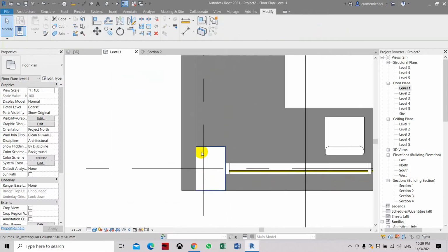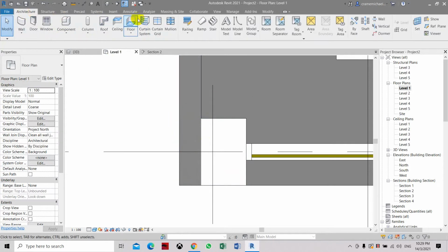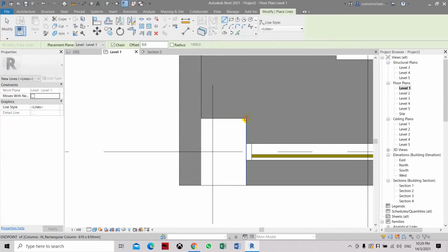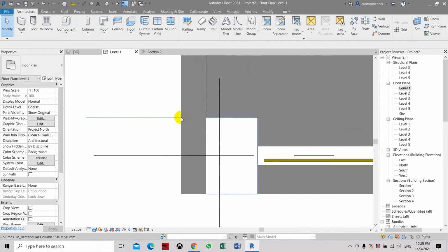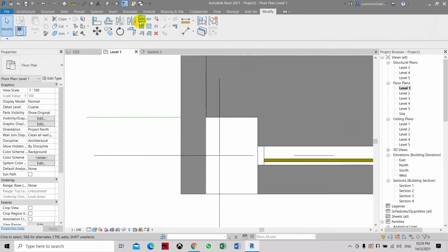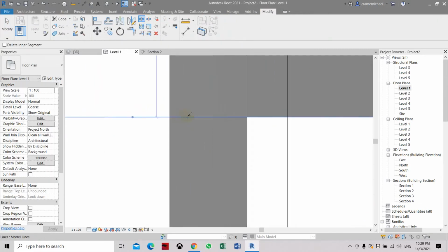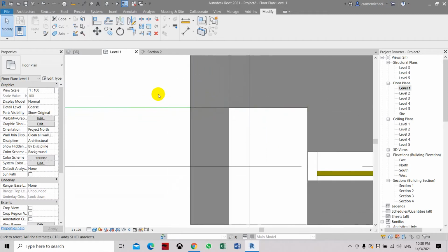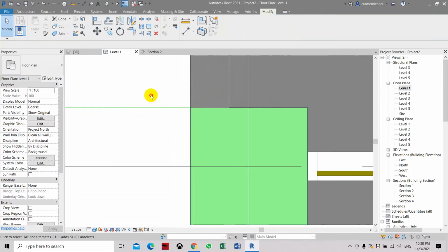Now we're going to cut the last part of the wall which has been extended until the corner of the column. So again, let's use a model line as our reference. Now we only need to create one line because we're cutting it at this edge. So we go to modify, split, select this line, make sure it's highlighted, then select again. You have to click twice, make sure it's cut, click escape twice, select the cut portion, the one we have to delete, erase the reference line.